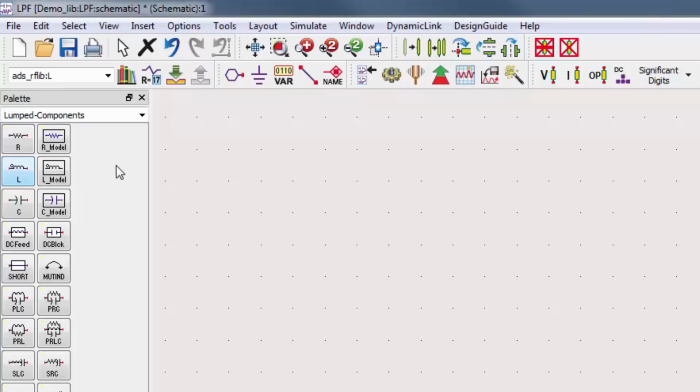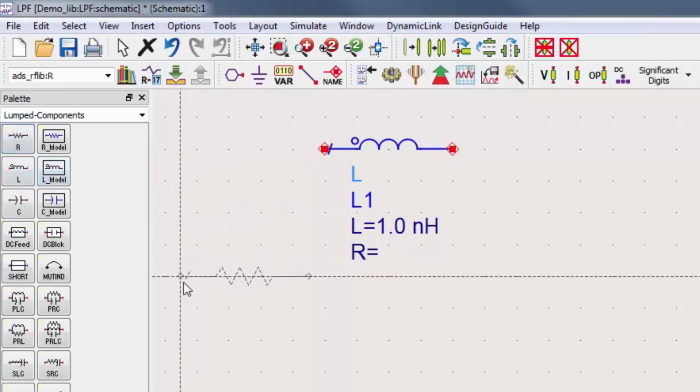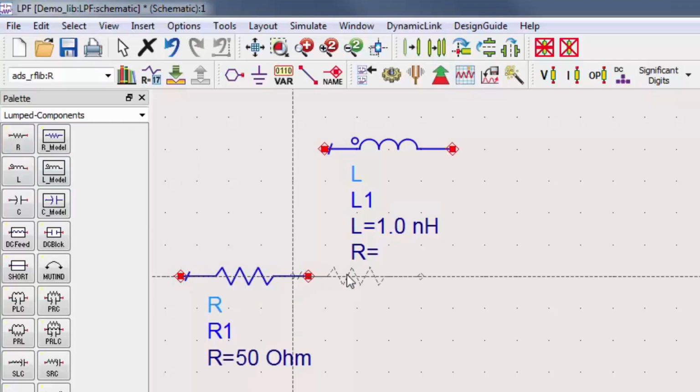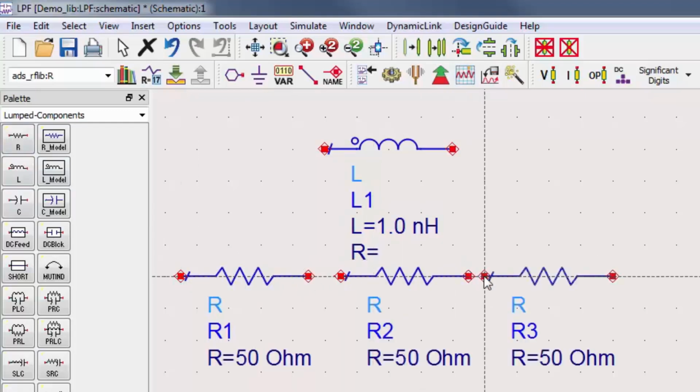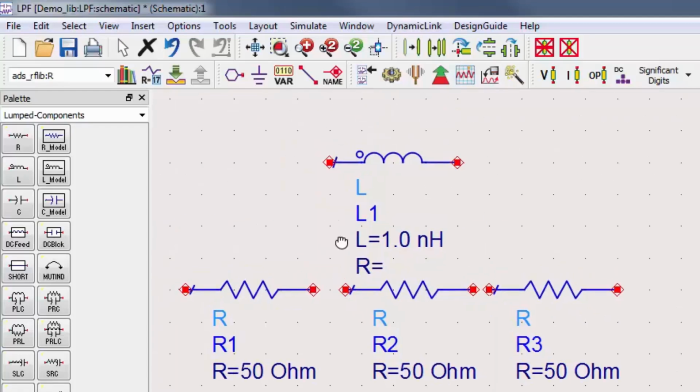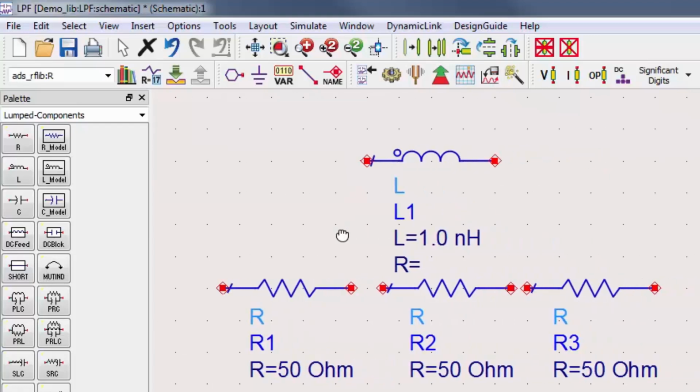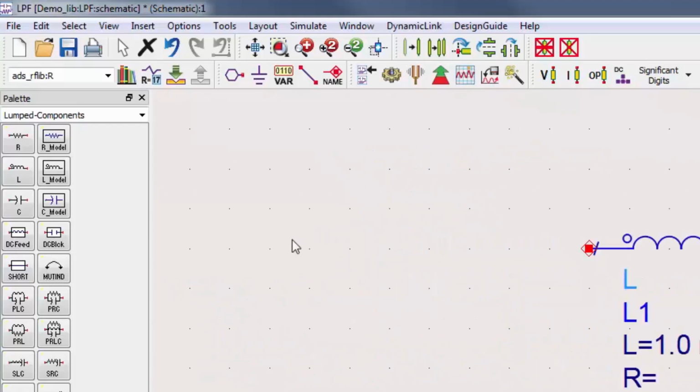You can place resistors or other components on your schematic by using a left click. Your mouse is the main tool here. Click grabs the component from the library. The escape key stops any commands, so each time I grab a component, I can keep placing it to the schematic until I hit the escape key. A right click pans the view and the mouse wheel is used to zoom in and out.